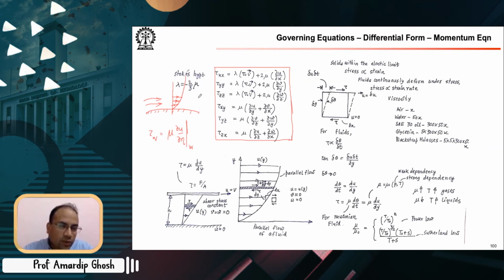When you study boundary layer theory, you will see that the wall normal variation of velocity is tremendous. It goes from zero on the wall to the free stream within a small extent. So the gradient of the u component of velocity is very large, and in the calculation of shear stress we look at that variation only.